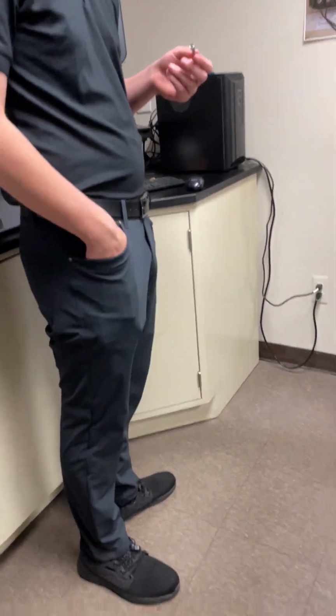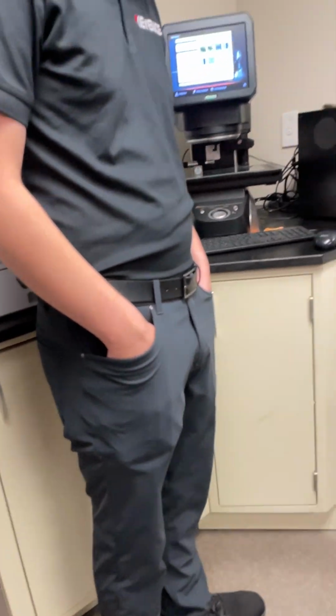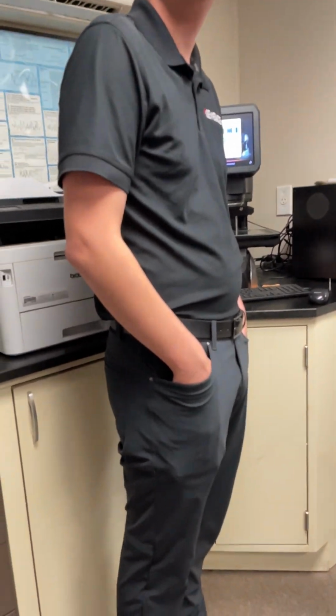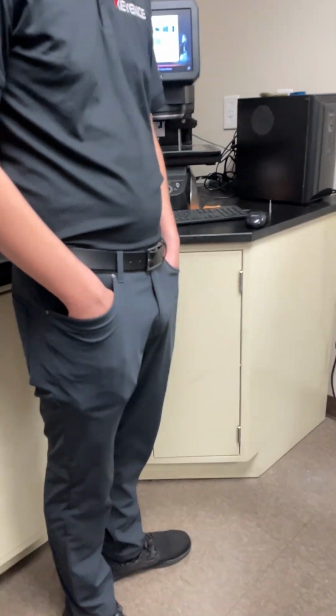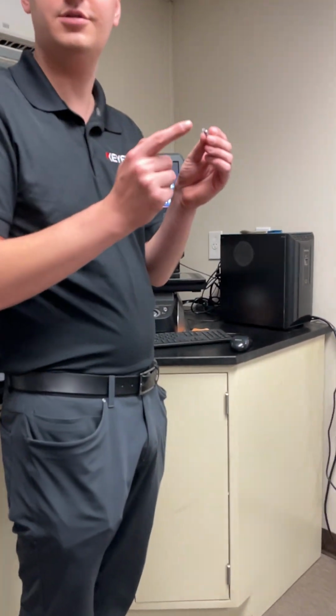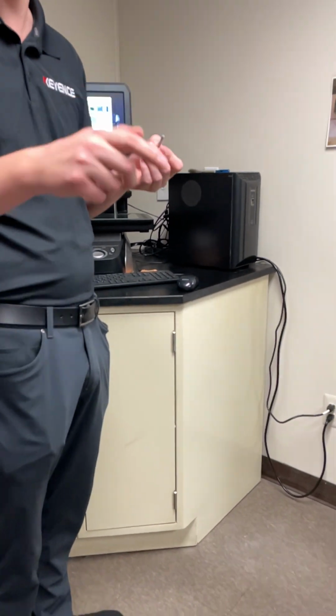So with the rotary, if we were to chuck up this part right here, it would identify the runout in the diameter. The single diameter, not from one to the other. It would do the single diameter. With the runout, you have to have a reference, like a datum of some sort. Whatever it is, you just click. It's just the order that you click them in.